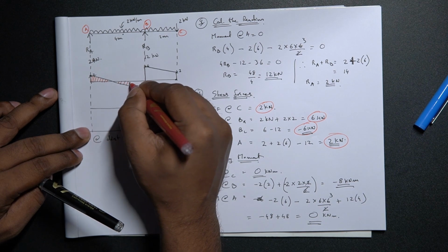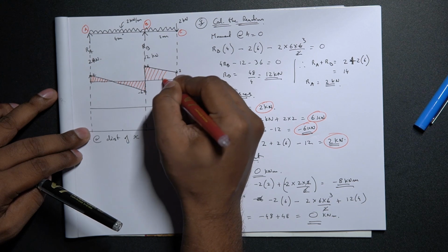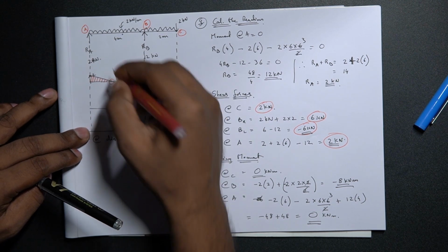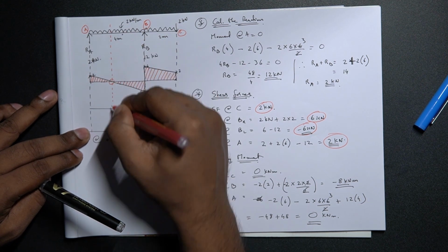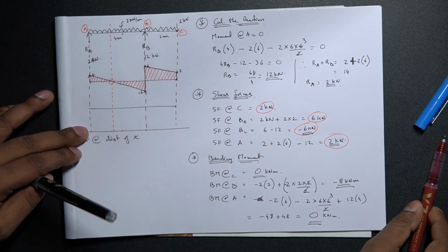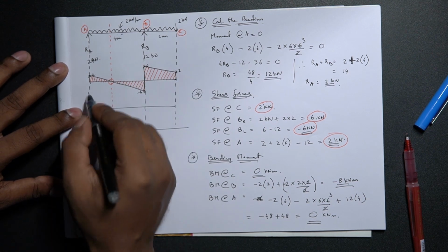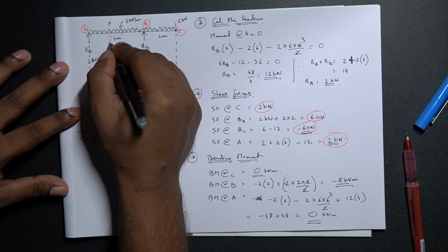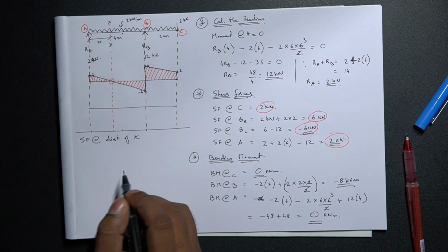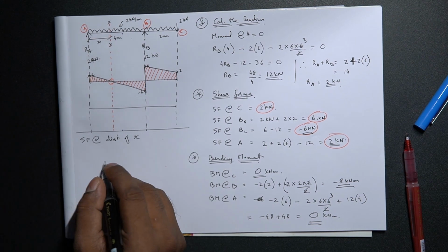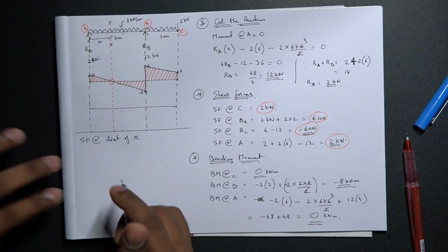you can see that we have a point where the shear force is absolute 0, this point. Now it is easy to identify this point as we can represent it diagrammatically. So the diagram would be much cleaner and more accurate if we do this first and come back to calculating the distance of the section XX. So now let's consider the distance of X from the support RA. Now calculating the shear forces at XX.